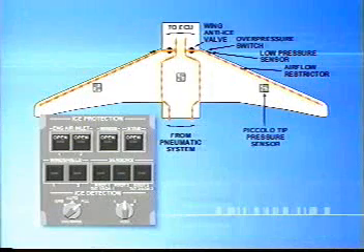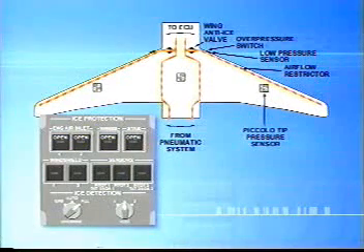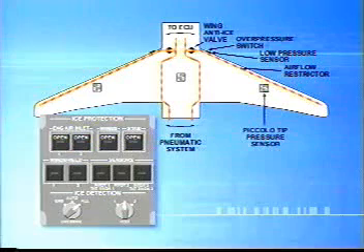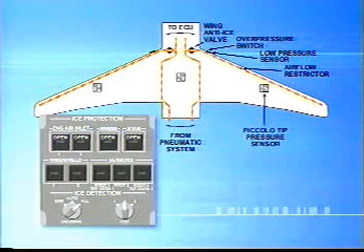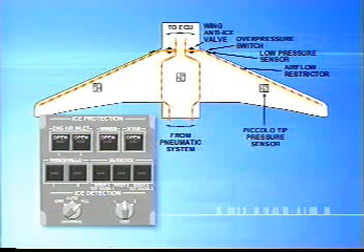Wing anti-icing operates only in flight or when wheel speed is above 25 knots on the ground. Operation is controlled from the cockpit by a button which closes the wing anti-ice valve when it is released, or allows automatic operation when it is pressed. An open light illuminates in the button to indicate that the anti-ice valves are manually or automatically commanded to open.